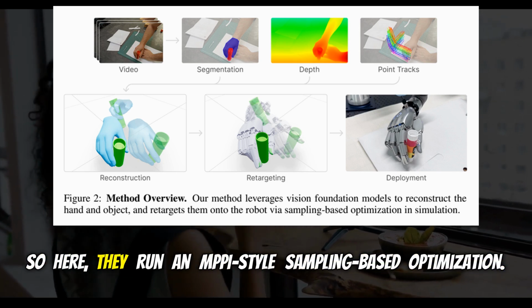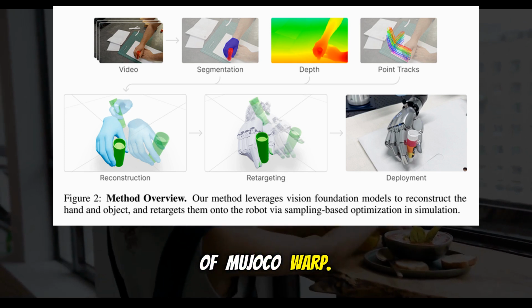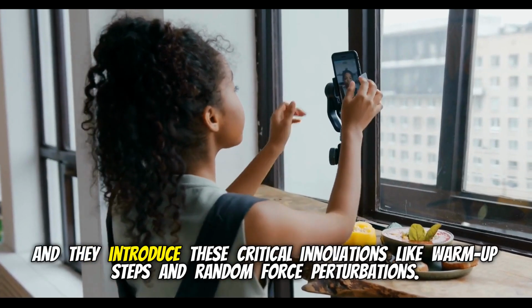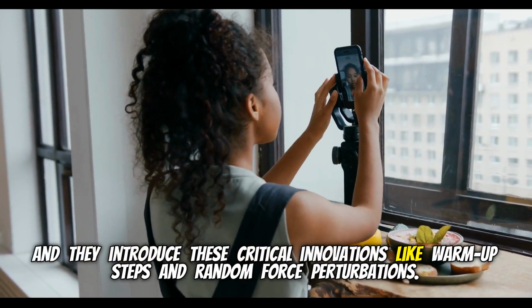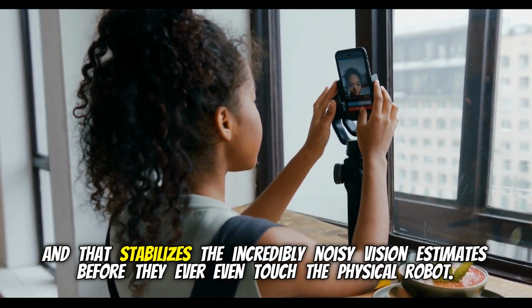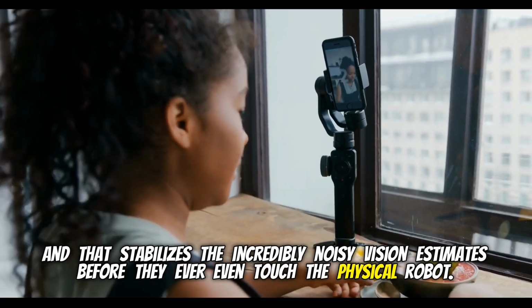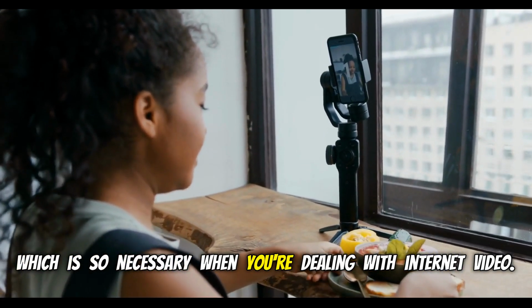So here, they run an MPPI-style sampling-based optimization. MuJoCo Warp. Right, you got it. And they introduce these critical innovations like warm-up steps and random force perturbations, and that stabilizes the incredibly noisy vision estimates before they ever even touch the physical robot. Which is so necessary when you're dealing with internet video.